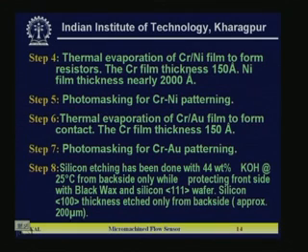If you do lithography in the next phase, you may face problems, because photoresist will not uniformly cover the entire surface, and its thickness may vary over the top and bottom. Then exposure will not be uniform over the entire wafer, and development and subsequent processes can have problems. In that case, if you really face the problem, you can go for direct deposition of the metal film, either by the lift off technique or by a direct vacuum mask technique. One advantage is that you do not have to bother about the chromium nickel etching solution.